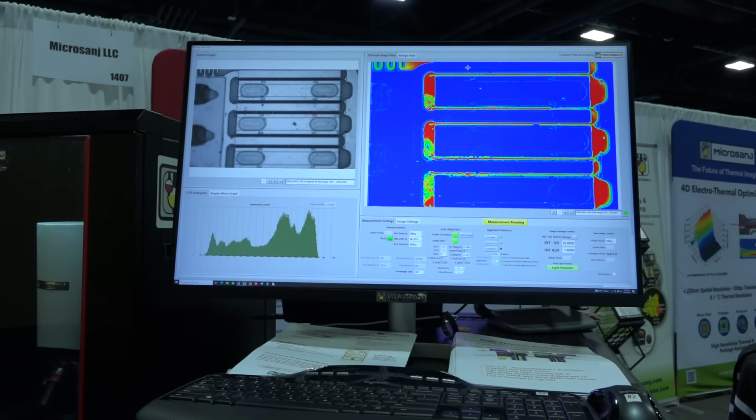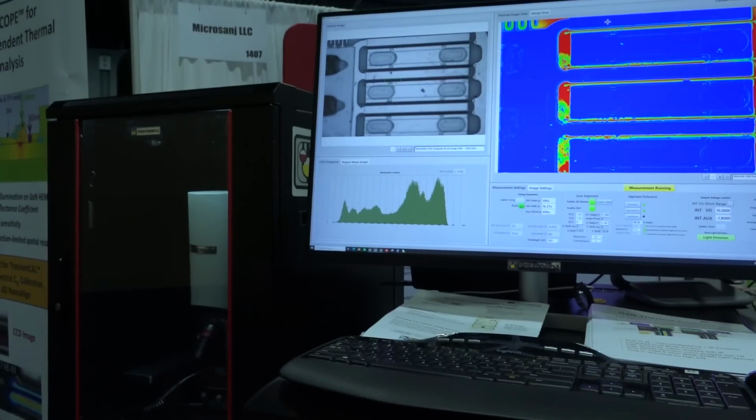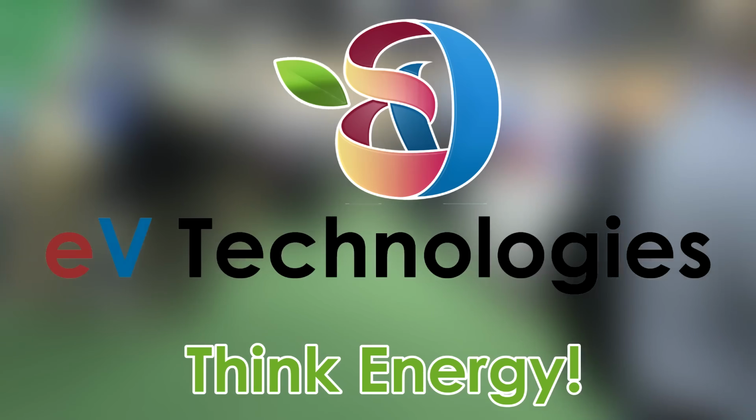There is another measurement they're doing which unfortunately doesn't have a live demo, but they're able to look at a phased array antenna, and let's say they have 64 antennas, and they can rapidly measure EM emissions through their thermal measurement. So you can quickly find out if a large-scale phased array has bad elements or it has some PAs that are not properly connected to the antennas, and you can do this rapidly in a production environment without doing any RF measurement, which is very different. So I'm curious to see how this will be deployed at large scale, but it's one of my favorite technologies on the show.